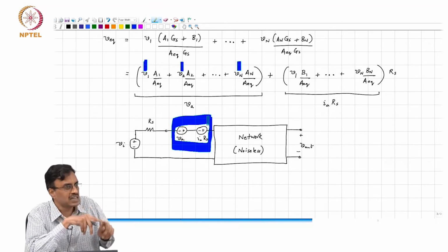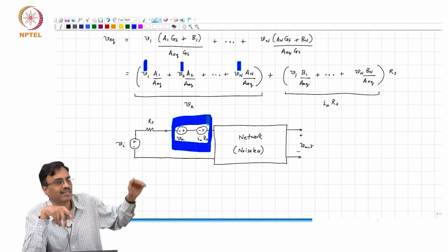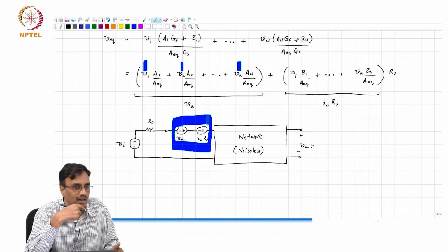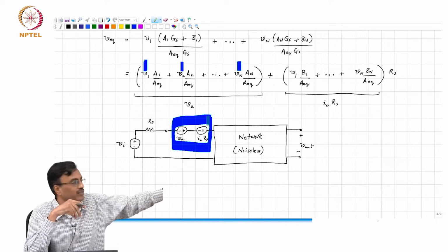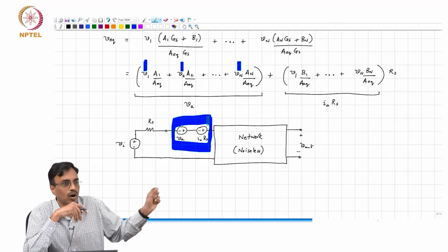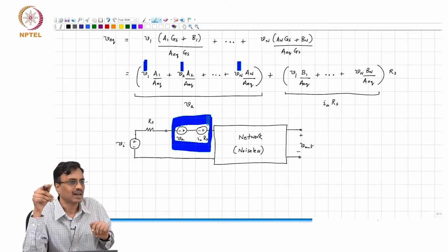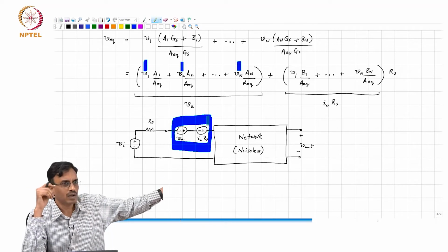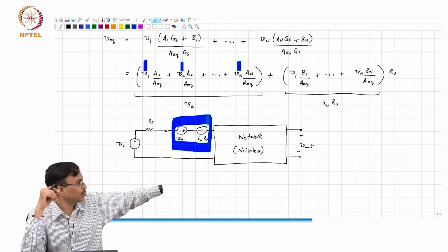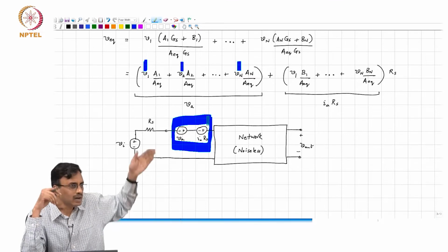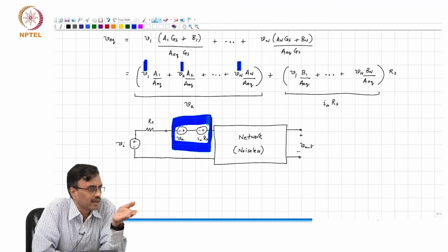So, if you want to achieve the same noise as Rs becomes larger and larger, the only way to do that is if the strength of that equivalent input noise voltage becomes larger and larger and must be proportional to Rs, because asymptotically the transfer function from Vi to Vo will fall off as Rs.